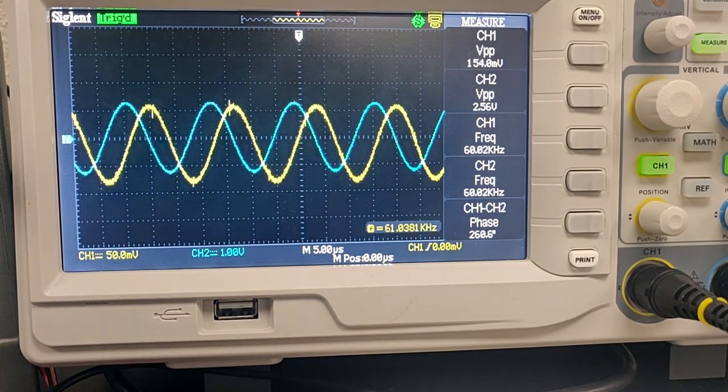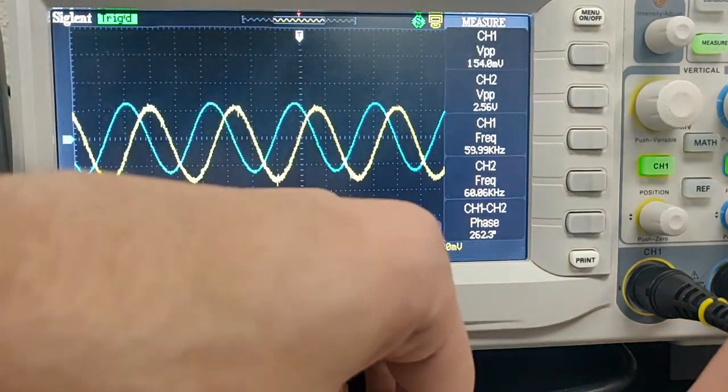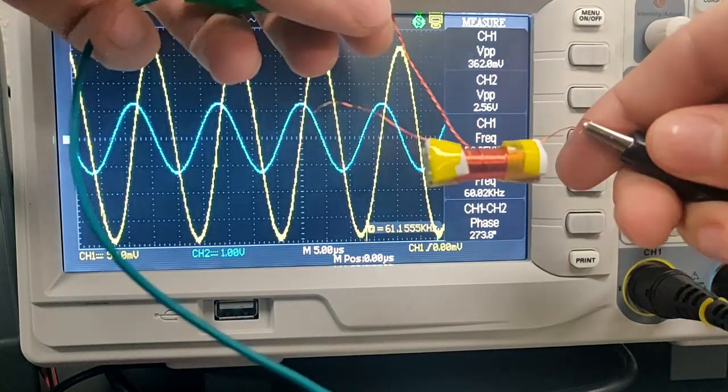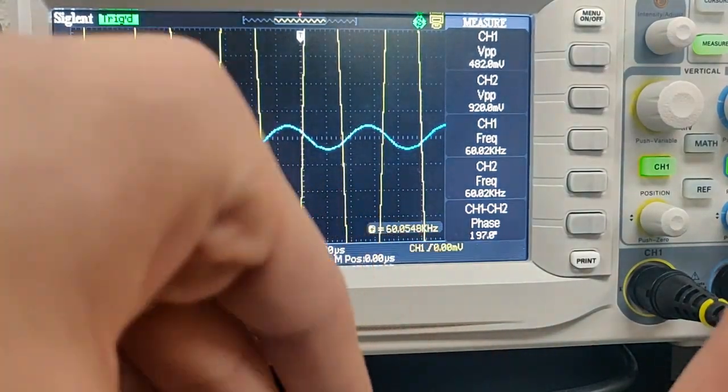And that makes sense. Like I said, the inductance is smaller, which is inversely proportional to the resonant frequency. So smaller inductance, larger frequency. Okay, now let's do the last one. So we're going to do the center tap short now. So changing this lead so it's right here.